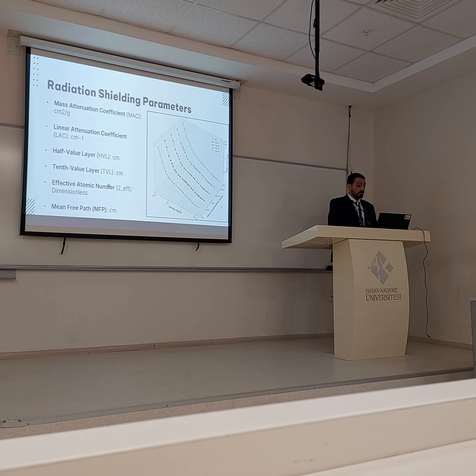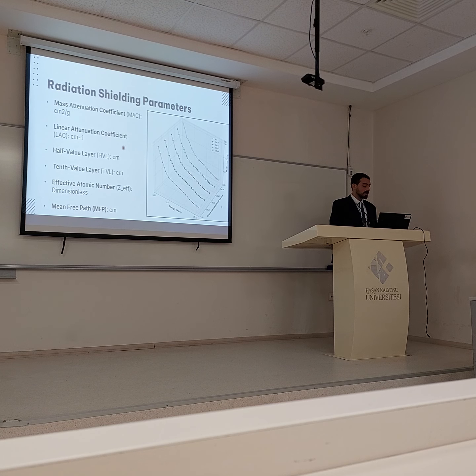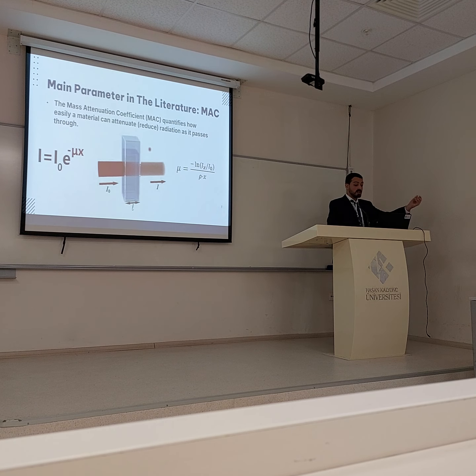Also, we have other parameters, not only the mass attenuation coefficient: we have the linear attenuation coefficient, the original idea of the mass attenuation coefficient, half value layer, tenth value layer, effective atomic number, and mean free path. But we will focus on the mass attenuation coefficient because it's the most common in the literature and the most effective one, because it considers the thickness of the material, as you can see here, and the density of the materials.